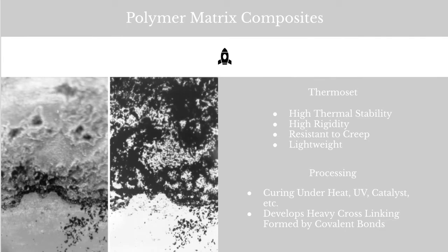There are actually three types of PMCs: thermoplastic, thermoset, and rubber, but only thermoset is considered for aerospace applications since thermoplastics form weak bonds, and rubbers, while having some uses, are not used for obvious mechanical and thermal reasons on structural parts. Thermosets, on the other hand, form extensive cross-linking and strong covalent bonds, making them better fit for these applications.